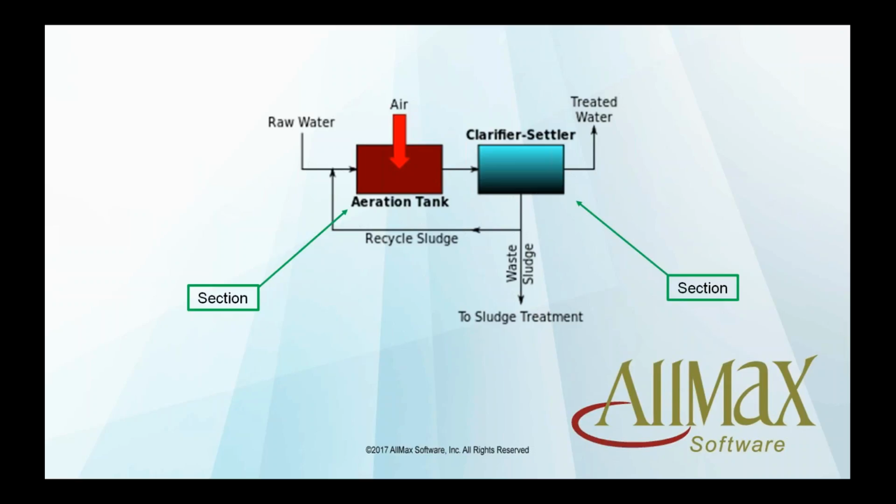For example, for an aeration basin, I'm going to have a removal efficiency of X for that time. Over this entire basin, the FM ratio needs to be this. Again, we're going back to that design criteria of what is needed to work.